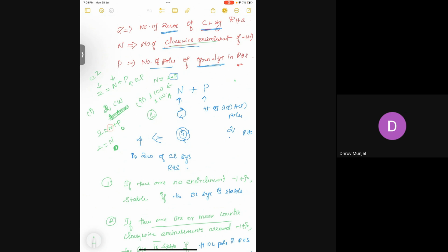Clockwise and anti-clockwise together mean there is one pole and one zero that compensate each other, nullifying the effect. So this is considered 0, and the second system is stable. If there were only one clockwise encirclement, the system would be unstable, but the counterclockwise one nullifies it.